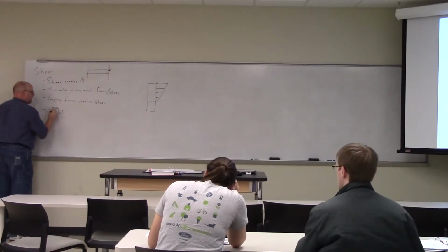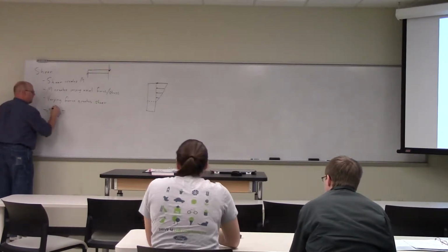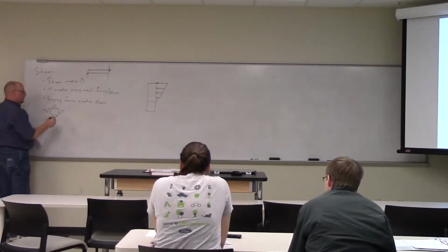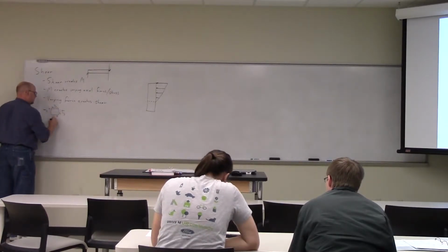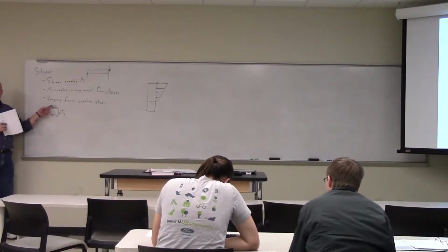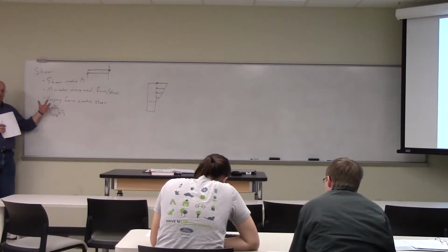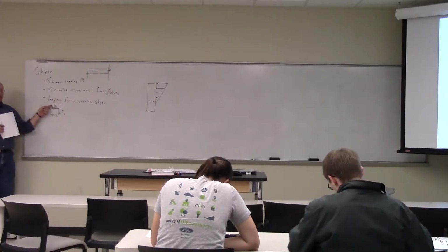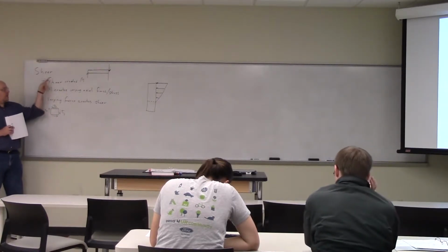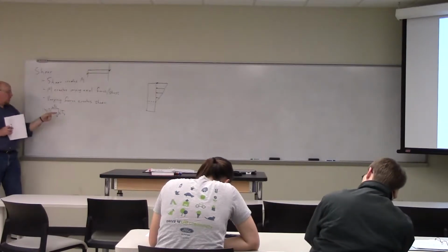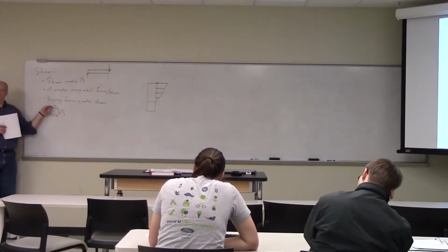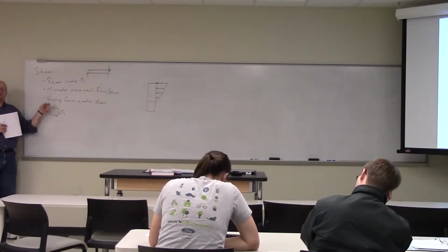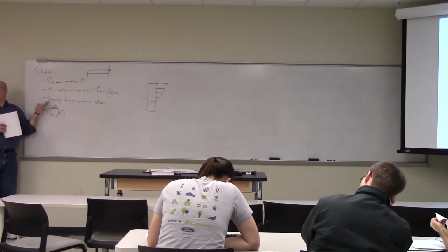But also keep in mind, from what we talked about before, that this is tau y, this is tau x. The tau x has to equal tau y because that moment doesn't rotate. Remember we talked about that back when we introduced shear stress. So the shear stress on this y plane is equal to the shear stress on the x plane. Because of all this variety here that gives us a little bit of confusion, we're actually not going to solve for tau y, we're going to solve for tau x. And then, because we know that tau x has to equal tau y, we solve for tau y.